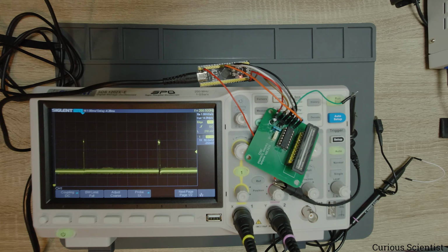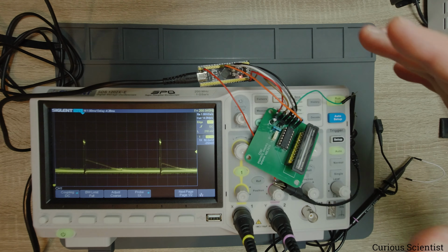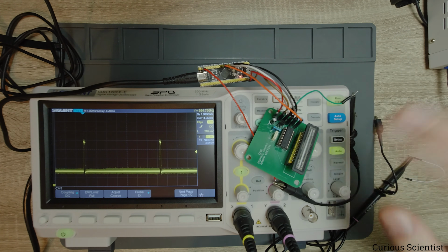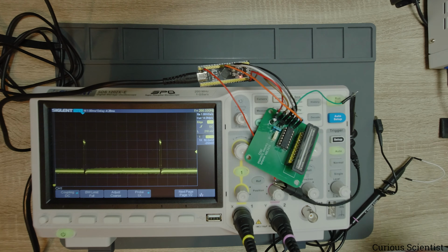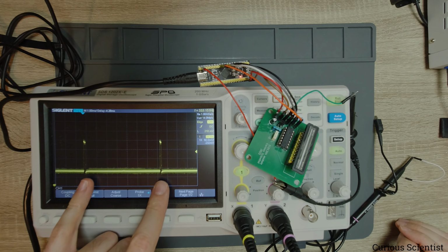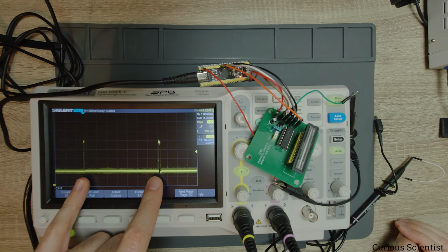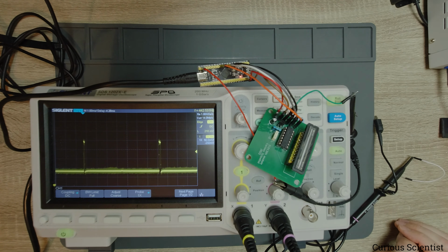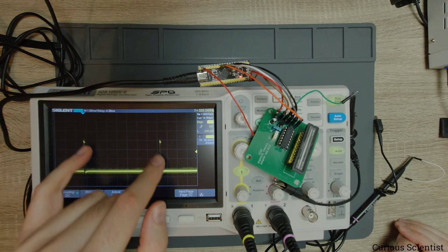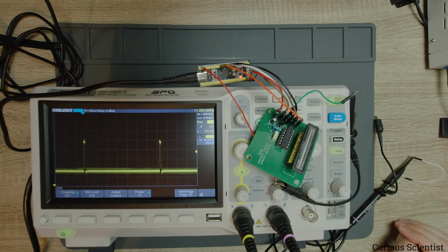So coming back to this circuit, now everything is just set up. I set up the timing and everything for the oscilloscope. So actually what we see in between these two peaks, these are the two initial dummy pixels when we start the timer, which triggers the ADC, but there is no data to read by the ADC because the rest of the things are not there yet.